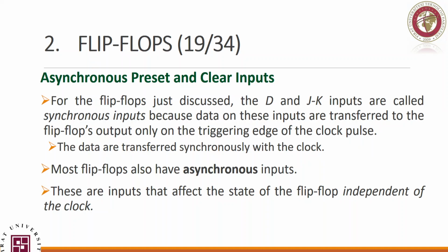and how they work. Now, for some reason, we may have something we call asynchronous preset and clear inputs. Asynchronous means what? It's not synchronized with the clock cycle. It's relevant to the operational process of the flip-flop. However, it affects its output. Meaning what? I can control the output of the flip-flop regardless of its own clock or the operational clock of that flip-flop. So in that case, we do not have a synchronization, and that's why we call it asynchronous.